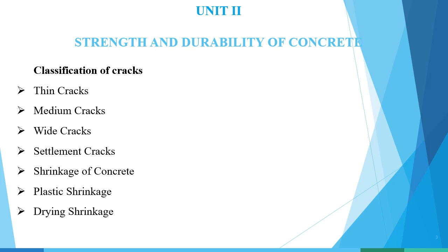Then finally the last one, drying shrinkage. Drying shrinkage in concrete is an inherent property of concrete. Shrinkage is one of the fundamental reasons for initial induction of microcracks in concrete. The mechanism involved is too complex. Generally, the pattern of shrinkage is a function of cement content, water content and water cement ratio. In practical terms, at a constant water cement ratio, shrinkage increases with an increase in cement content.